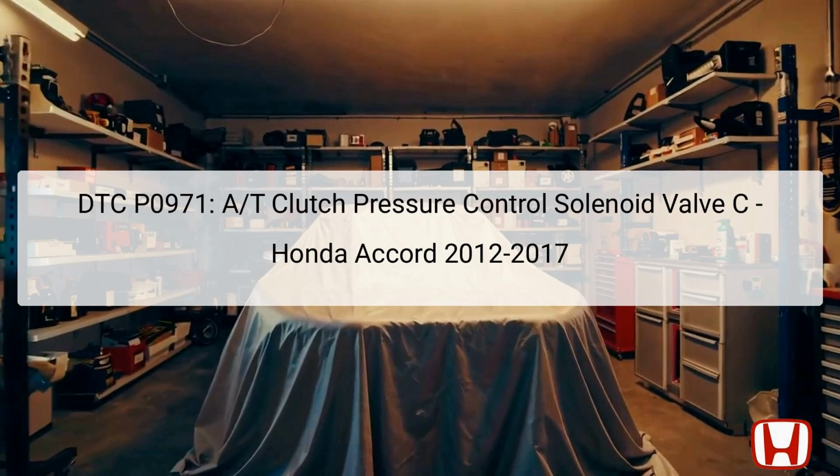When there's a malfunction, it's primarily related to the electrical circuit, which implies that mechanical issues in the transmission are not at fault. As a result, if this error code is detected, the vehicle defaults to a fail-safe mode, restricting shifts to only first, second, or fifth gears. This slide outlines the purpose of the solenoid valve and the implications of its failure in the vehicle's transmission operation.